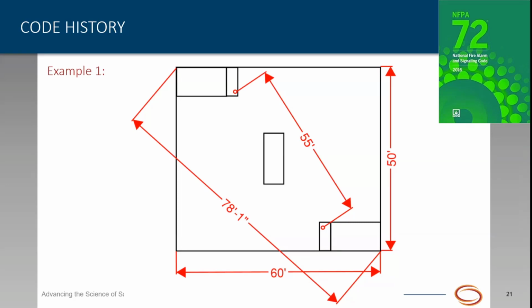The 1/3 distance calculation is the 78 feet times 1/3, which is 25.7 feet approximately. So we can place a Class X or Class N riser in each of those comm or electrical rooms, giving us a separation of approximately 55 feet. So this would meet that exception in NFPA 72, and we would not require survivable cable as long as those circuits were Class X or Class N.